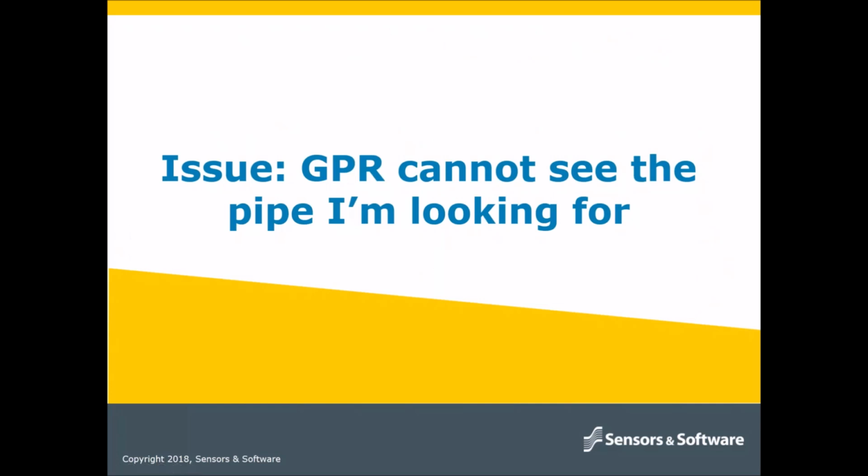It's very important for utility locators to recognize when lack of GPR penetration is the issue. In some cases, this is very easy to do. For example, if the utility is known to be about 10 feet deep and the depth of GPR penetration in the area is nowhere close to 10 feet, say 4 feet, there is nothing that can be done to suddenly see 2.5 times deeper with the GPR. When a utility is deeper than the maximum depth range of the GPR, a different locating technique must be used.